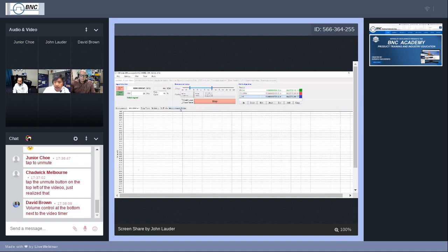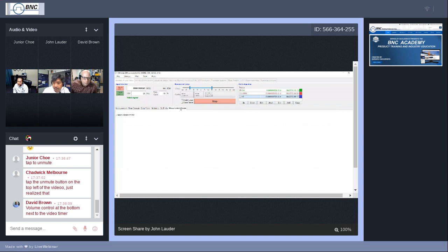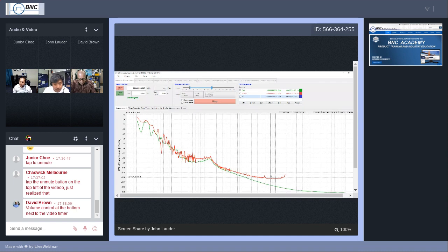And again, the device will start to lock to our pulse signal. It's locked right away. It took about 12 seconds to lock for a bigger pulse width. As I mentioned in the video, the shorter the pulse width and duty cycle, the longer it will take to lock. So it's now making some correlation of the pulse.